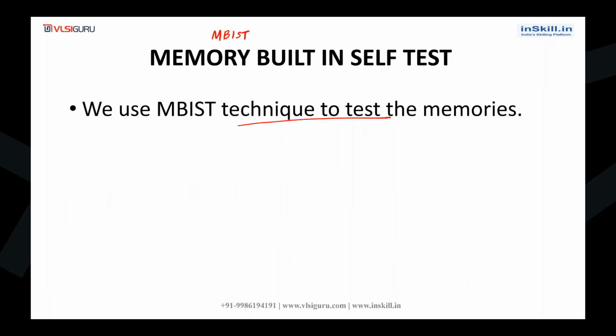So during our MBIST course, on our first day, we'll try to understand the various memory fault models, like the stuck-at fault model, transition fault model, address decoder fault model, coupling fault model, like that.